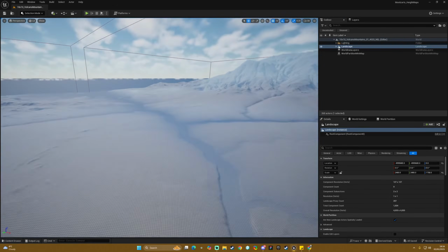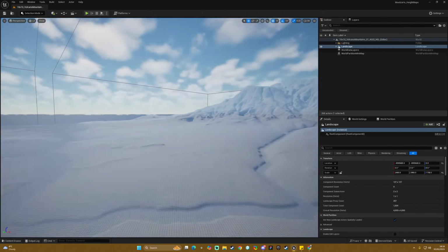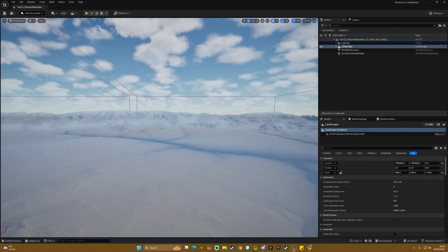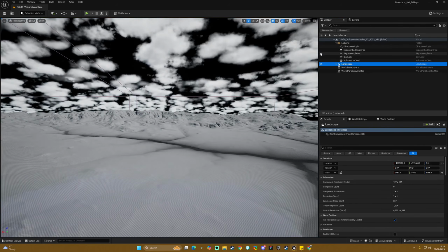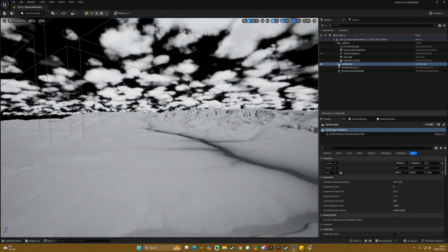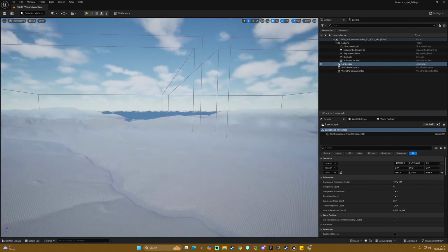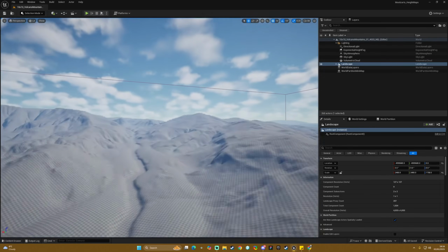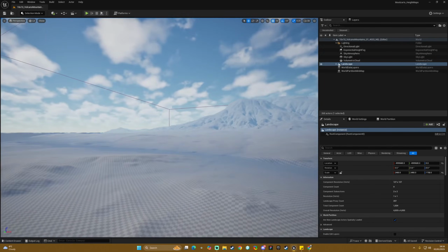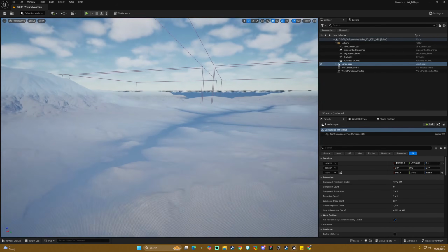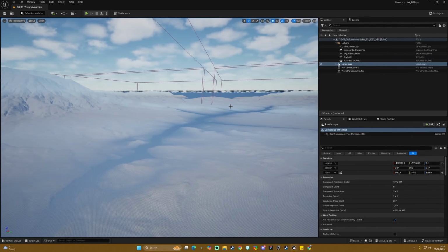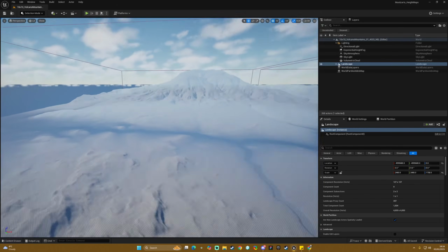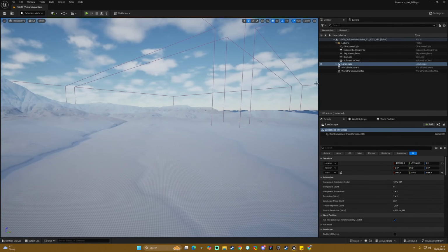I'm then going to quickly add those to our lighting folder and save. So we do get these kind of strange issues with the fog and the sky atmosphere. I'm pretty sure it's the sky atmosphere causing these issues, and I haven't really dug into the specific reason. There's going to be a lot of potential reasons, which is why generally I use Ultra Dynamic Sky as my lighting option, because it gets rid of a lot of this crap.